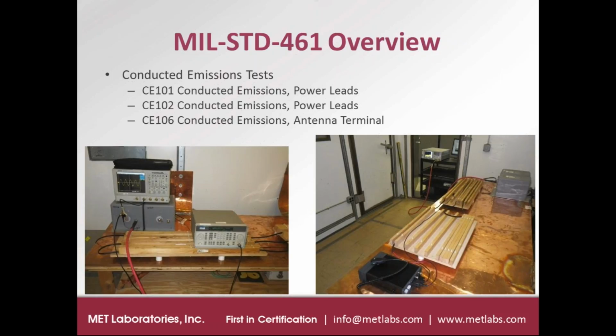So the first several tests that are listed in Section 5 are conducted emissions tests. So that means that we're going to use measurement equipment like a spectrum analyzer or an oscilloscope to measure the emissions that are generated from the EUT. And that means when the EUT is normally used, it's going to create as an unavoidable byproduct of its electronic operation harmonics and other electronic noise that will conduct out of its cables, even though it's not designed necessarily to conduct out of those cables. And that interference can conduct into other equipment that's connected to the same power bus or that's connected to the same data cables as the equipment under test.